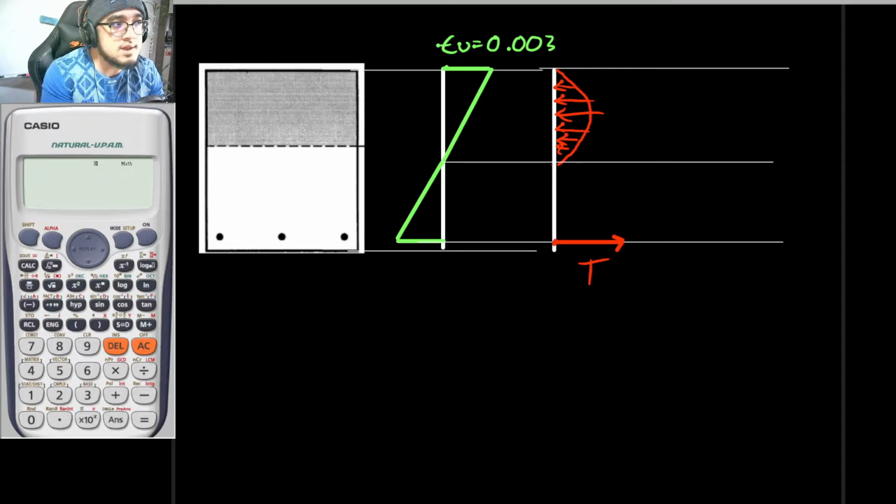So this is basically its approximate area in rectangle. So by the way, once again, since we cannot solve for this area, researchers before have found out that the approximate uniform stress that is equivalent to this area would now look like this.